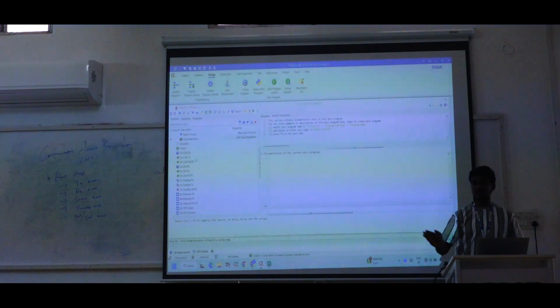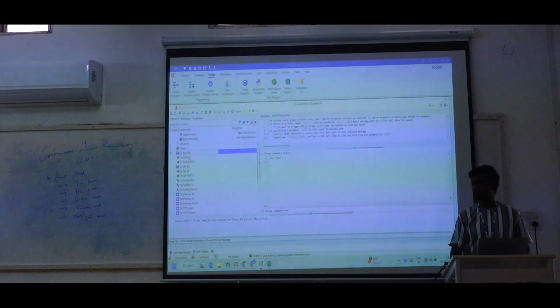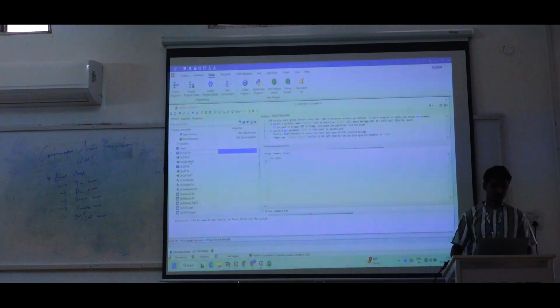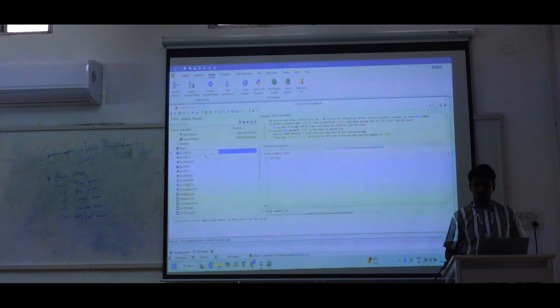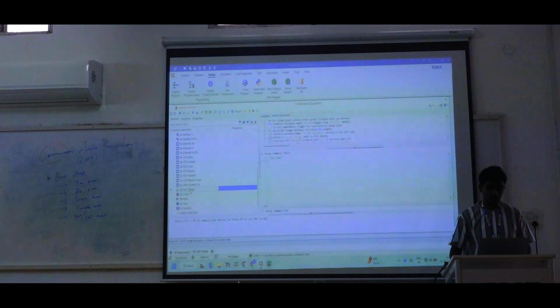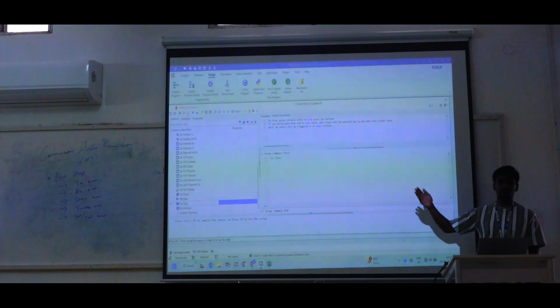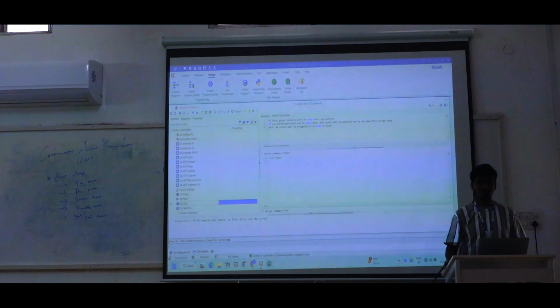If you enter the scripting tab in any tool, the common ones are variables, timers, for CAN, RX, for a particular CAN protocol, CAN RX, TX, and then CAN 3 TX is an additional feature in this tool, but the common ones are RX and then TX, which is enough. The last things are on timer, on variable change, on start, on stop. These are common in any tool for CAN scripting.